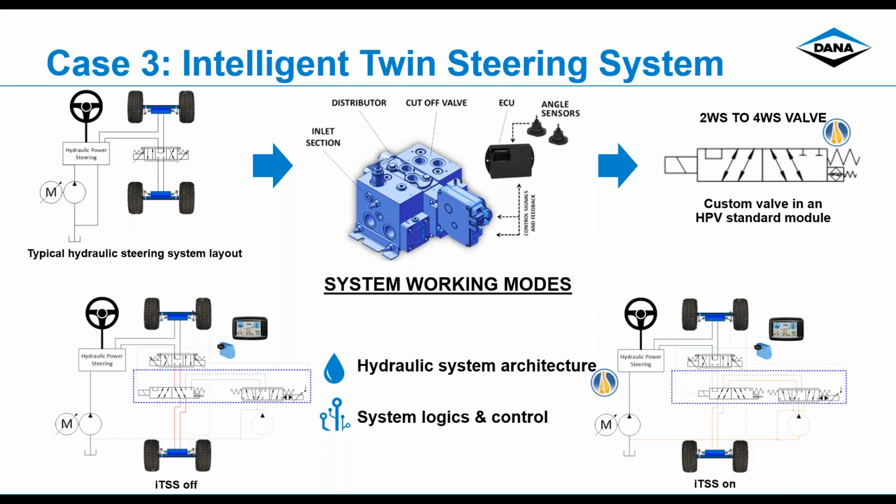Okay, in this way it is not possible to independently control the rear steering angle and the front steering angle. But with the concept introduced by Dana, with a standard HPV configuration, with the addition of a dedicated logical control and a custom valve for the spool of the HPV, it is possible to transform, let me say, a typical hydraulic steering system into an advanced one.